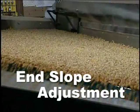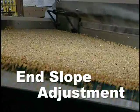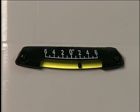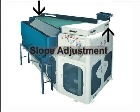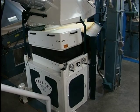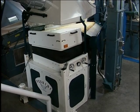End slope is the angle of the entire deck surface from the feed point to middling discharge. As stated earlier, the end slope is preset and is not typically modified by the operator. You can verify the angle of the end slope by checking the bubble level located on the high side of the table. Adjustments to the end slope can only be made with the machine turned off and properly locked out. Please contact ARROWCORP or refer to your user's manual if it is necessary to make this adjustment.